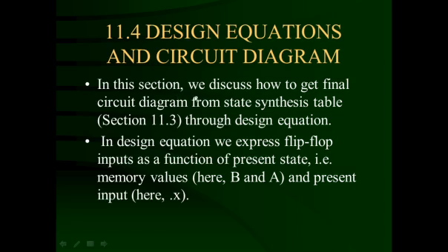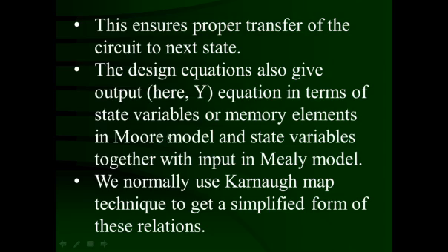In this section, we discuss how to get the final circuit diagram from the state synthesis table through the design equation. In design equation, we express flip-flop inputs, that is JA, KA and JB, KB, as a function of present state, that is An, Bn, and memory values here, that means Bn, An, and present input, that is going to be X or Xn. This ensures proper transfer of the circuit to the next state.